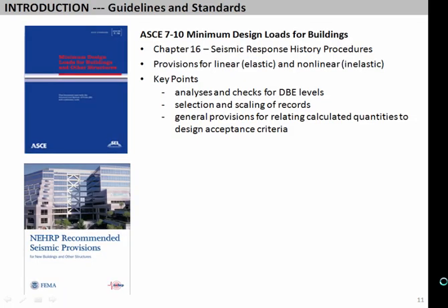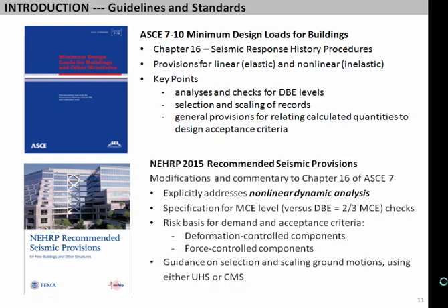And I think correspondingly, if you look in practice, a lot of this builds on the tall building documents, relating to ASCE 7, the loading criteria. And as Marshall described, ASCE 7 is really where we go to define ground motions and the hazards and so forth. ASCE 7 really didn't give much guidance on how to do a dynamic or a nonlinear dynamic analysis, but that will be changing with the next edition. You can get a glimpse of what's coming in NEHRP 2015. Marshall talked some about it, but it has a new draft Chapter 16 for ASCE 7 that gives more guidance on nonlinear analysis. And in fact, that really embraces and was modeled after a lot of the ideas that were developed through the tall building initiatives.